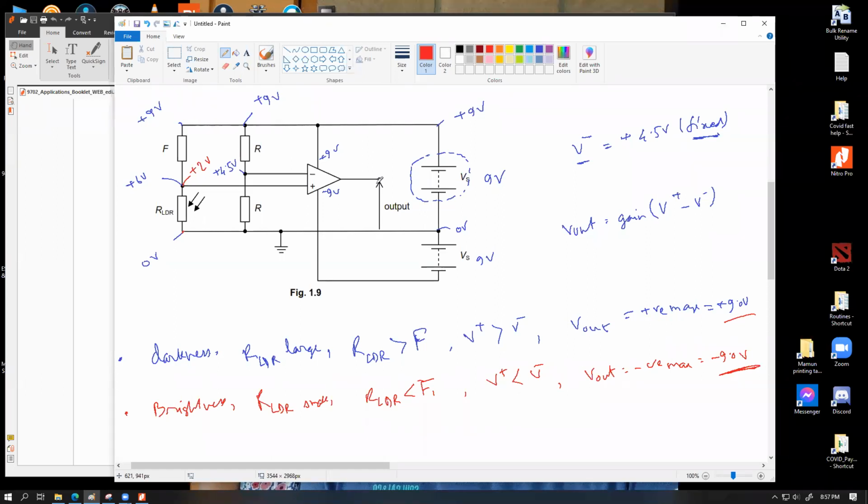So here's the deal. Let's say you want to have a signal out of this circuit when the device becomes dark, for example, if you want to use this circuit for a street lamp. Street lamp means that we're going to keep this LDR above the cover of the street lamp, where it is illuminated by the sunlight. So when the sun comes up, the LDR will be exposed to the sunlight and the street lamp should go off, and when the sun goes down, the street lamp goes on, which means in the darkness the street lamp should go on. So if we want to use this circuit to respond to darkness, this circuit is going to give us a positive voltage, and we can very easily connect a 9-volt LED light over here,